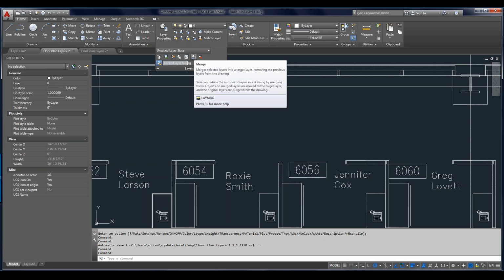No. I mean, you could. Yes, you can't. So if you had a palette or something where you added a macro that would set a current layer and then insert an XREF, or a toolbar icon where you do that, but there's no way to just say anytime I insert an XREF, put it on layer XR.